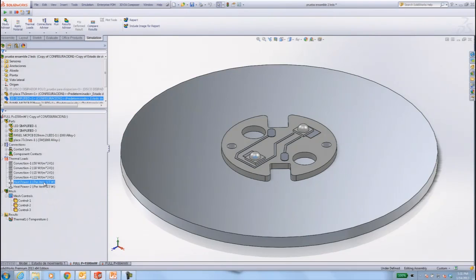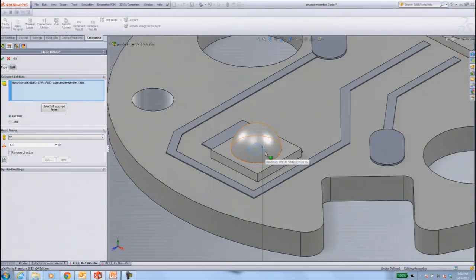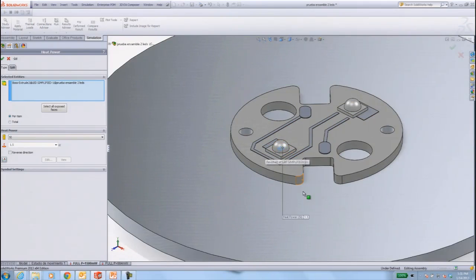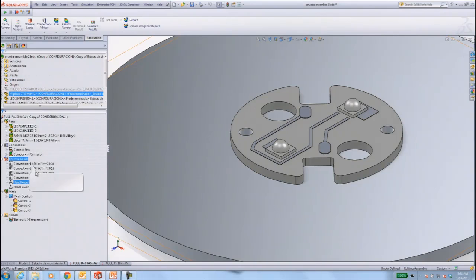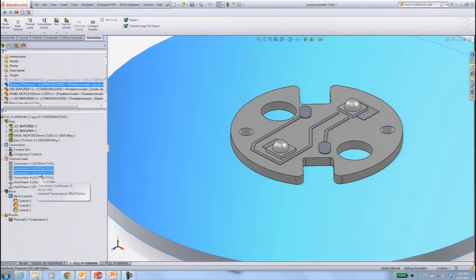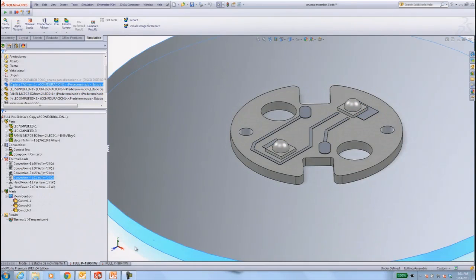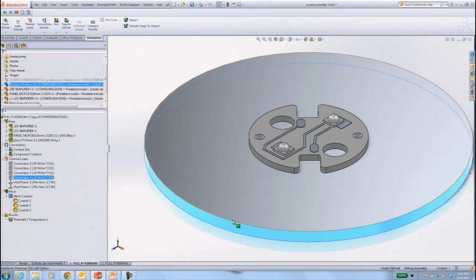There you have the convection coefficient. This was obtained through the laboratory. We ran a lot of full-scale tests with the customer, and after running this, you will see the results, and they match very, very well. These are all of the convection coefficients. You have to specify all the convection in every surface in contact with air, right?